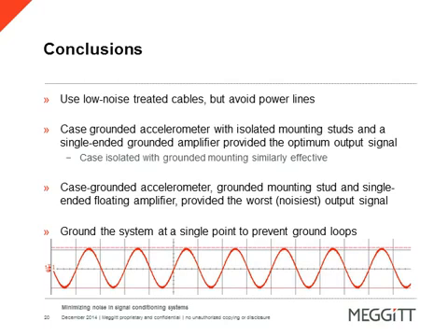It's good practice. Based on these good industry practices, tests were run with various accelerometer mounting schemes, and you saw those on the slides. To show the benefit of using low noise treated cable, a single-ended piezoelectric accelerometer grounded with an isolated mount, and additionally grounding and isolating case designs were compared to verify the best combination of grounding designs. Low noise cable and grounded and floating amplifier settings all had to be taken into account.